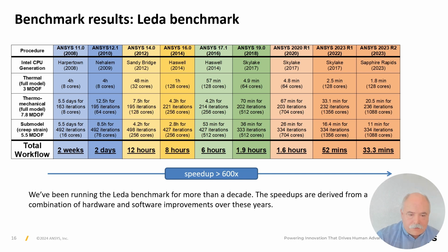Okay, so actually this goes back to an actual customer project that we did in 2008. And the simulation is actually 3 different ones. We start out with the thermal simulation, and use that thermal temperature field as an input for a thermomechanical simulation. And in the end, a submodel gets boundary conditions extracted from that thermal mechanical model to do a creep strain analysis on a little piece of PCB with an integrated circuit on top of that.